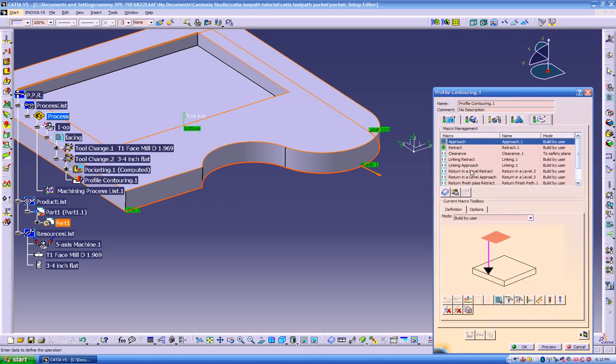And we have to approach it. We have to do a circular, horizontal, axial, because we don't want the end mill to plunge right into the part right here. So we kind of want the tool to come in very nicely, lead in and lead out over here. So we're gonna put approach, then we're gonna go back, build by user, and we're gonna go to a plane.